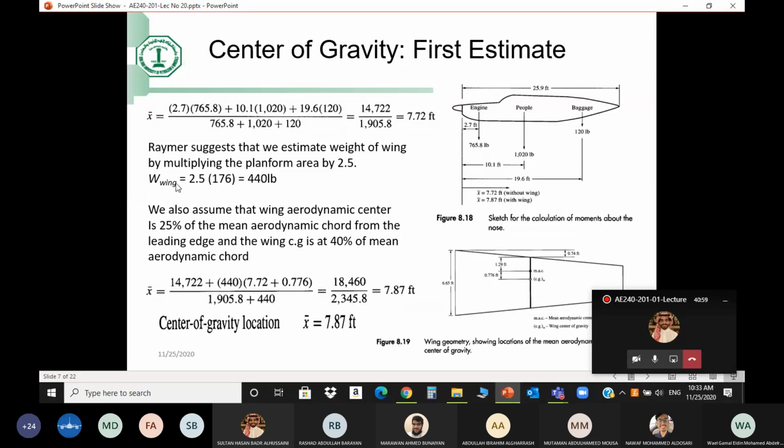So you can look at what's the factor for aerobatic aircraft. This factor is 2.5 for general aviation aircraft. It's about 9 or 10 for fighter aircraft. So I would say aerobatic aircraft will be somewhere in between, because they are expected to have high G loading. So maybe not 2.5, maybe 4 or 5. And we are going to try the value and see if it makes sense. In section 4.7, you will get a little bit more accurate way to estimate that.